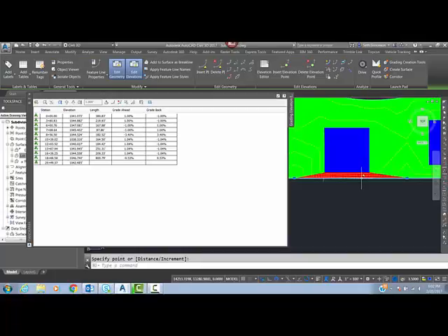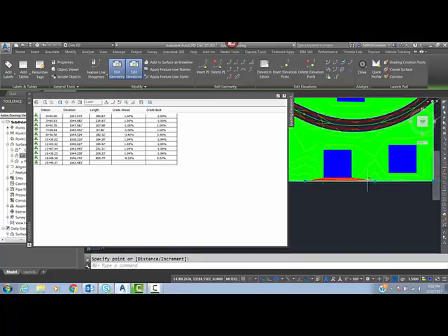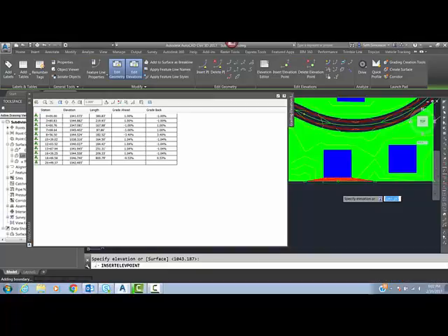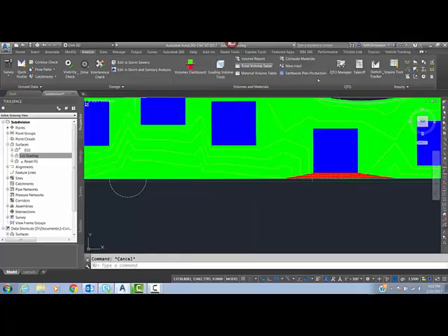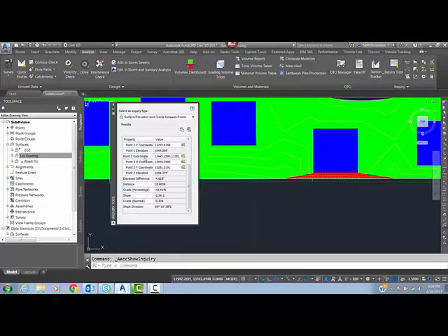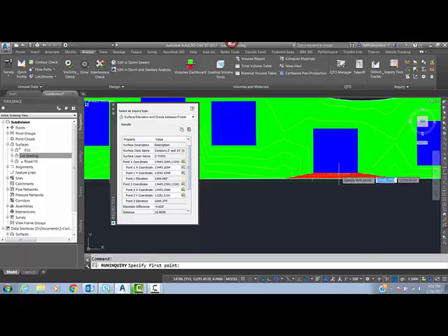Come to this side here. So again, if I put an elevation point in between here, we might end up with some stuff getting fixed. Again, it might still be kind of steep. Yeah, it looks like it's kind of steep. So again, if I close out of this, take a look at my inquiry tool and do some analyzing of what that grade is between the two.